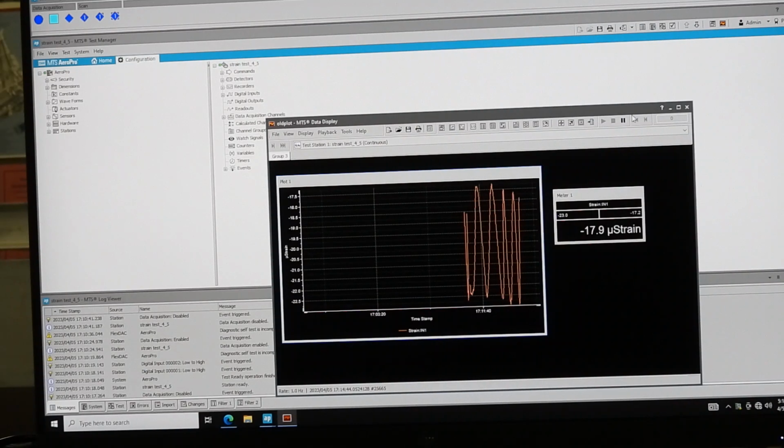So you could, for example, if you took pins 3 and 4, jumpered them together, and then hooked them back in there, you will have the issue, because you're telling it 0 volts. If you unplug it, now we're back in the scenario of a floating input that's picking up whatever charge is sitting around. I'm not telling it to be grounded, I'm not telling it to be at a certain voltage, it is undefined. Don't tie your data acquisition to a signal that is undefined.